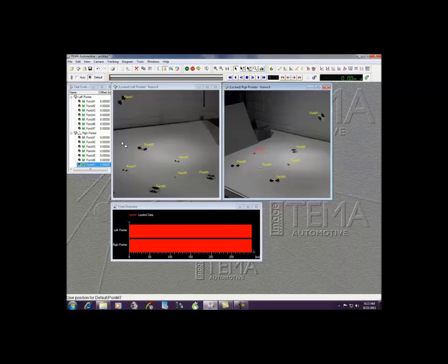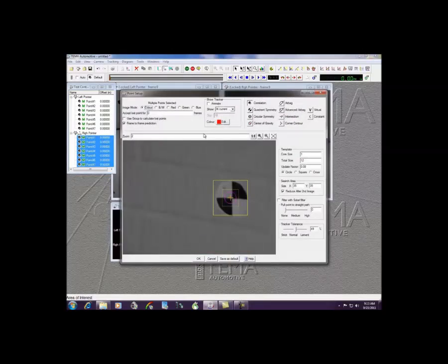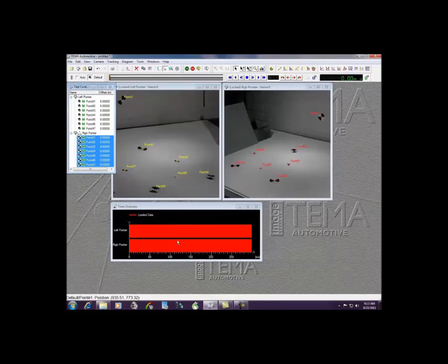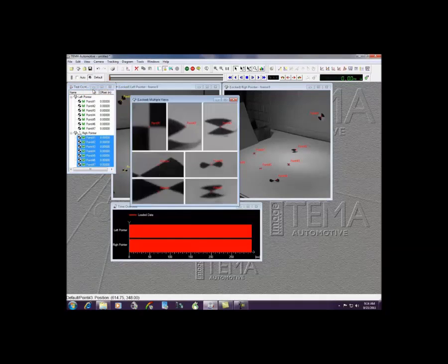To obtain accurate positioning, we will reset the points to the quadrant targets so they lock onto the targets. We will use the Show Window option to check that they're all set accurately. If they are not, and because it is a quadrant marker, you will need to use the Alt key if you want to adjust them.